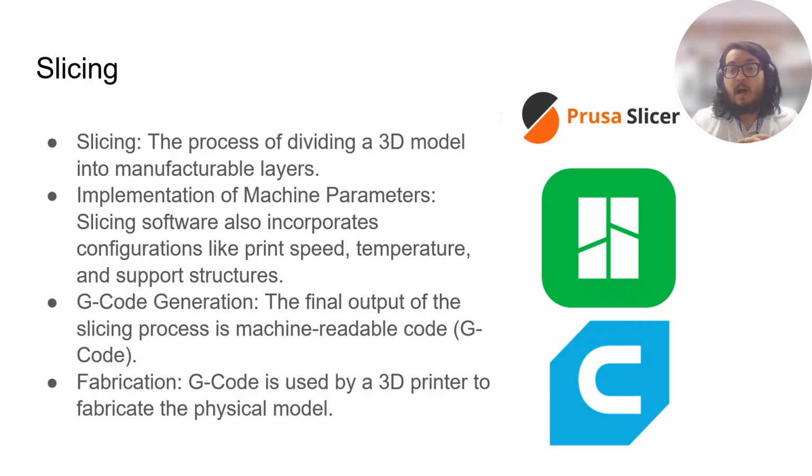So if you open a G-code, for example, that will create a rubber ducky, you see that you have thousands and thousands of lines of XYZ coordinates where, if you're following it, you're actually drawing your rubber ducky in a layer by layer manner. Can you write G-code by hand? Yes. Should you write G-code by hand? Absolutely not. As I said, it's thousands and thousands of layers. That's why we have slicing software to do this job for us.